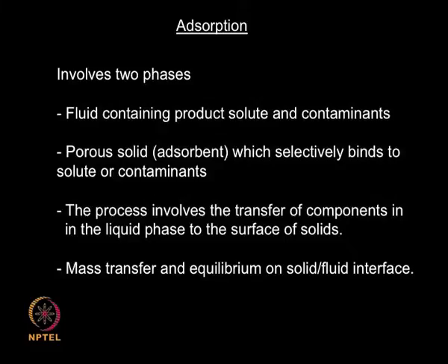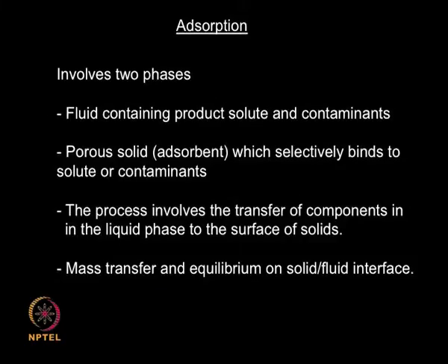So depending upon the mass transfer, if the mass transfer is very fast I will perform the adsorption very fast. If the mass transfer rate is very slow, the adsorption also will be very slow. So I need to give sufficient time for the solute to get adsorbed, and depending upon the equilibrium concentration I will decide how much of solid I need to add into the slurry. So the mass transfer and the equilibrium determine the thermodynamics and the kinetics of the process. Mass transfer determines the kinetics, equilibrium determines the thermodynamics, understand.